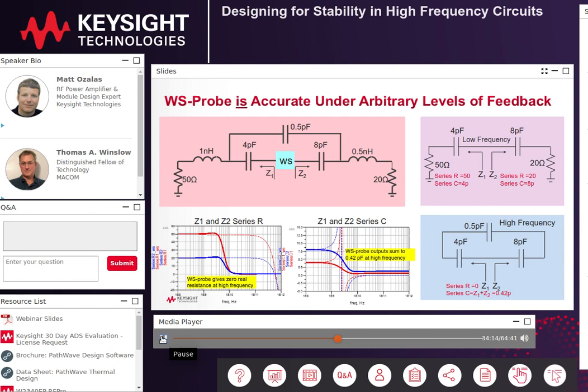I can't get into any details about how it does all of this, but if you look at the high frequency range of the series capacitance plot on this slide, you will see that the bidirectional looking capacitances show up in series to the expected total capacitance of the closed loop, 0.42 picofarads. Now, I strongly recommend that you build and study the circuit in ADS 2020 and drop the WS probe and the S probe in the center of the node as shown in the slide and run the simulation.